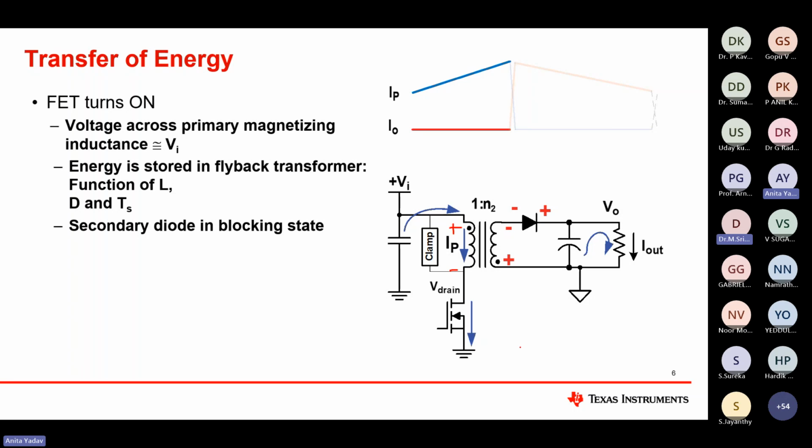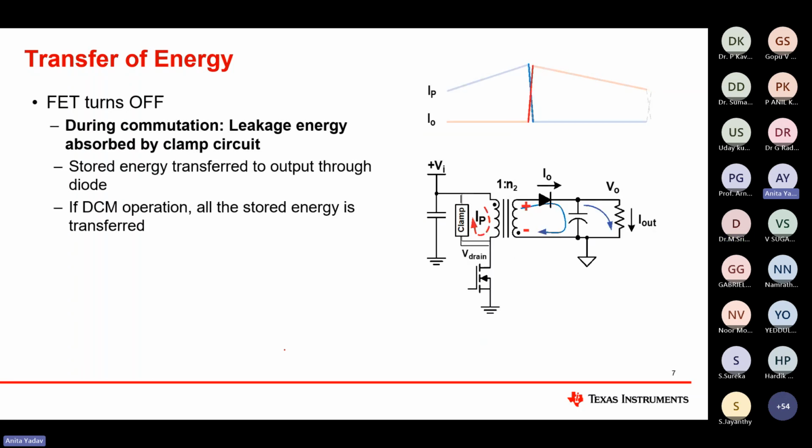And then we go to the second phase, which is the commutation time. Basically, before turning on the secondary side, we have the magnetizing inductance, and at this node we will get the total capacitance. This is basically the sum of the parasitic capacitance of this FET, the parasitic capacitance of the transformer, and the parasitic capacitances formed for any reason on your PCB.